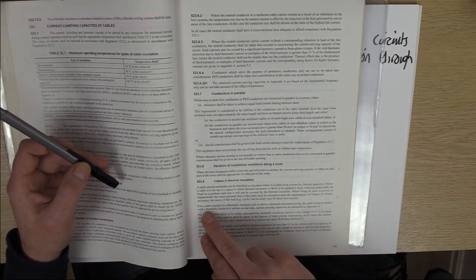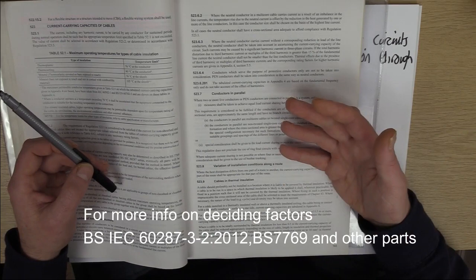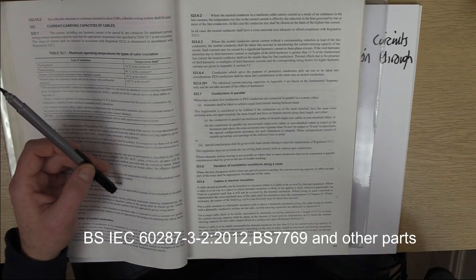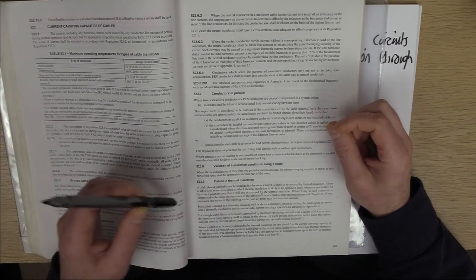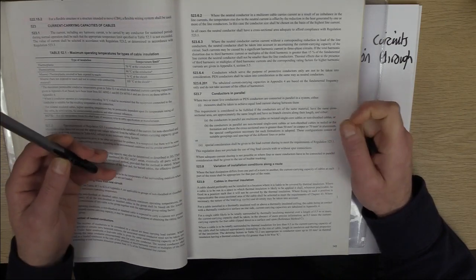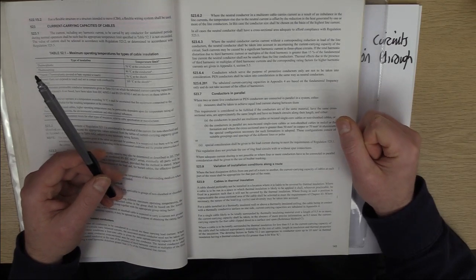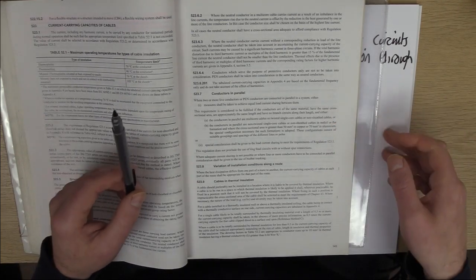And you keep reading down here, and it essentially says if your single cable is likely to be totally surrounded by thermal insulating material over a length of 0.5 meters, so just 500 mil, the current carrying capacity should be taken in the absence of more precise information as 0.5 times the current carrying capacity. So it halves the current carrying capacity, which basically means we're going to have twice the cross-sectional area. So, avoiding insulation is definitely the way to go.